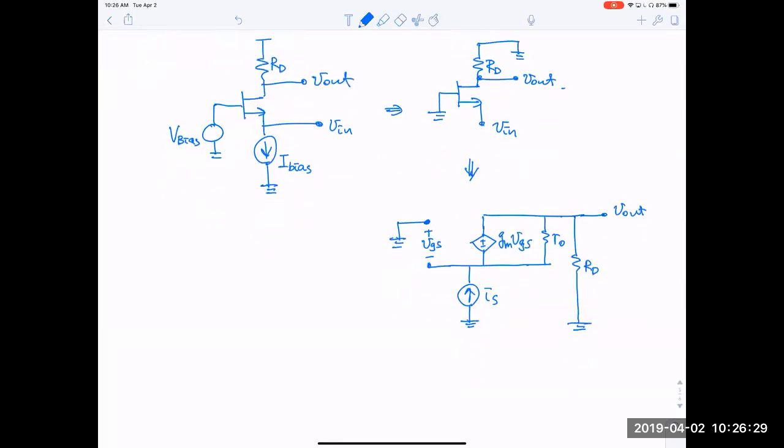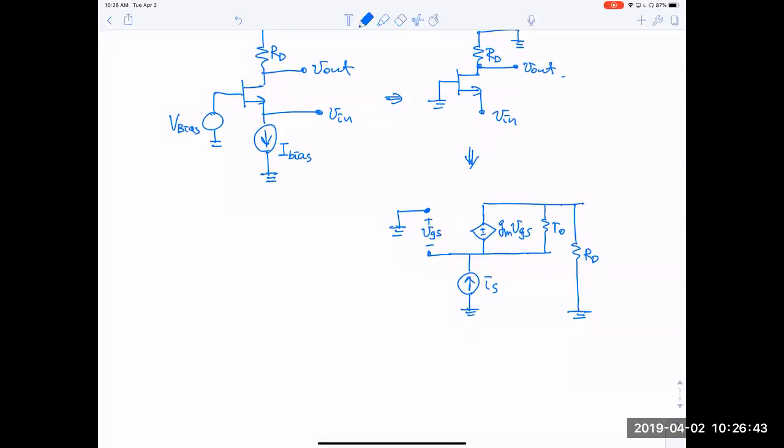All right. So this circuit is more commonly used as a current amplifier, rather than as a voltage source. To estimate a current gain, I make RL equal to 0 first. So basically, I measure my output current here, I out, and this is actually a short circuit here.